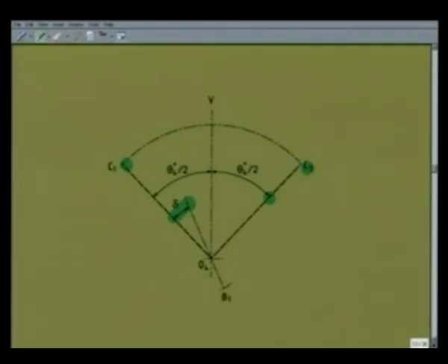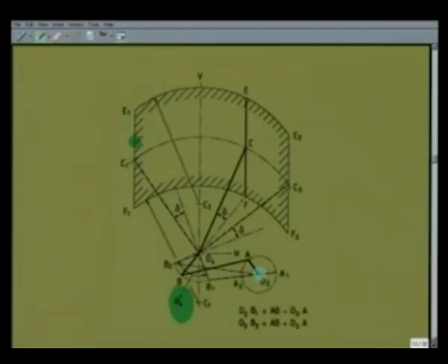So let me pose a problem that modifies this design, but you are allowed to change only the crank length O2A, this coupler length AB, and the angle delta to satisfy three requirements, namely the wiping field should be symmetrical about the vertical line O4B, and the width of the wiping field, that is the horizontal distance between these two extreme positions E1F1 and E2F2, is say 450 millimeter to the same scale, and there should be no quick return.